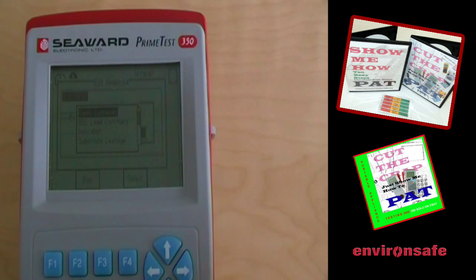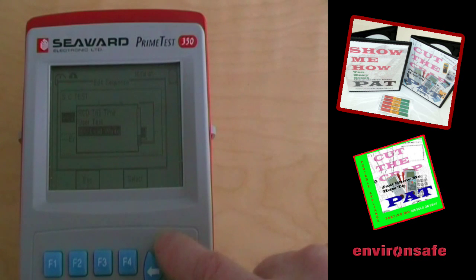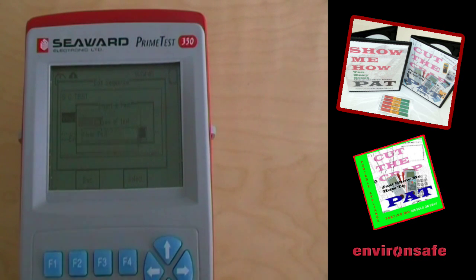Earth continuity, IEC, insulation, substitute leakage, PE conductor current, RCD trip, IEC wiring, visual. Well, we'll put a visual in because we want a visual check. Insert. We are looking for user test, so select that. We want a visual on the case, so we'll OK that.